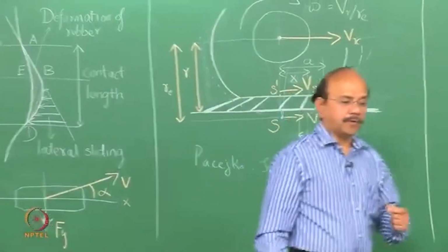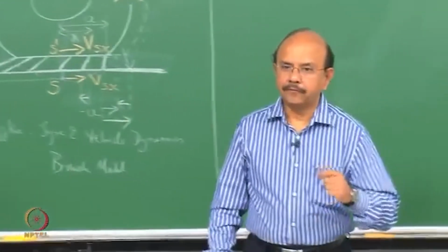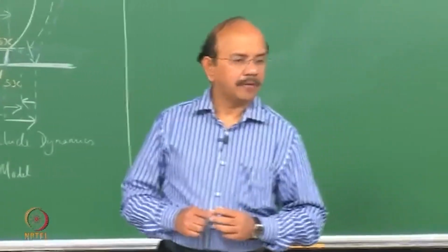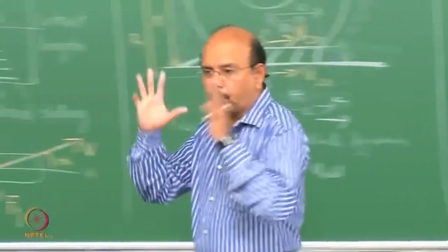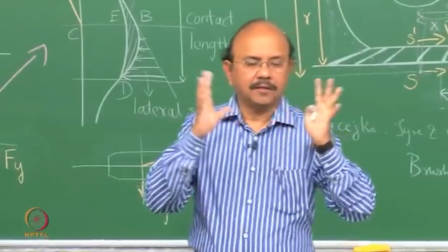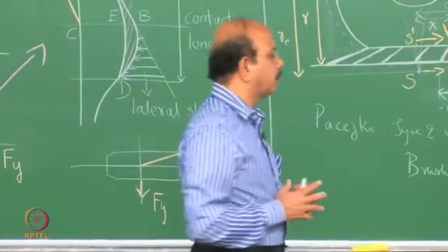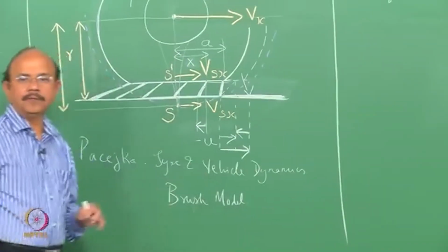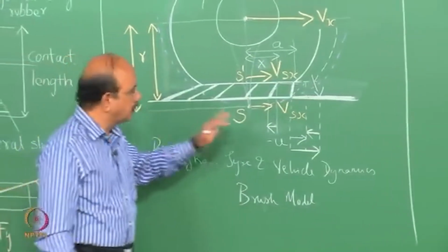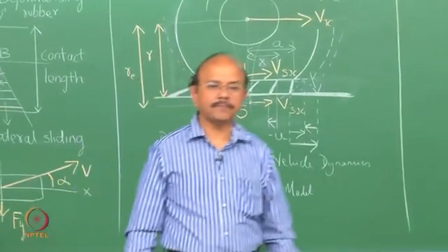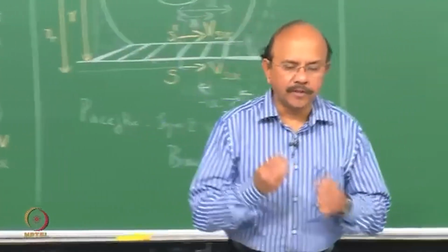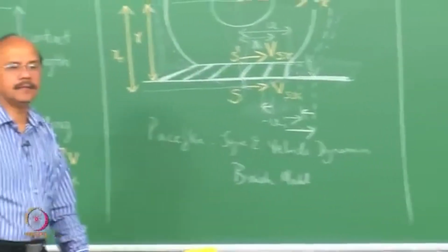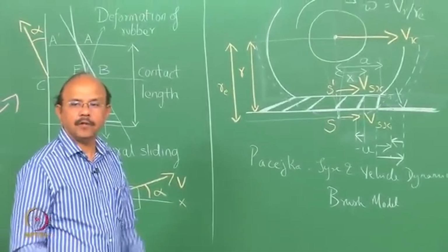There are very complex models available for the force development in tires, and I'll give you a very broad picture in the next class about what tire models are available for modeling the longitudinal as well as the lateral forces. But this model brings out the physics of the tire behavior in the longitudinal direction.